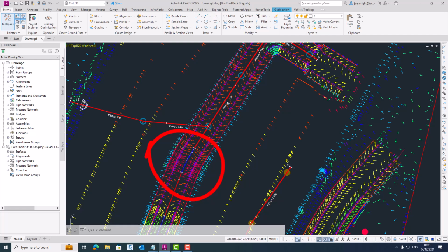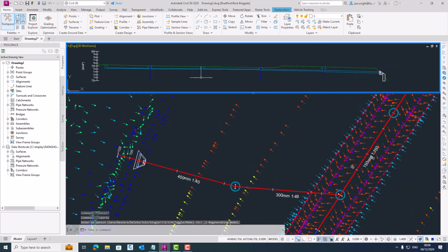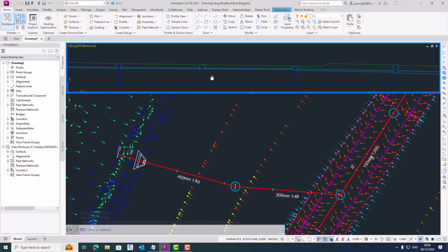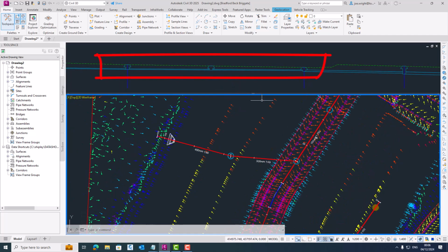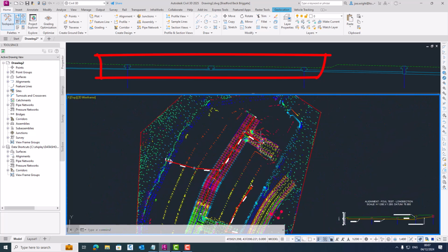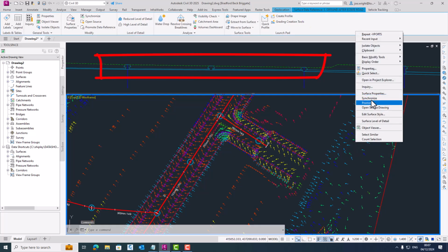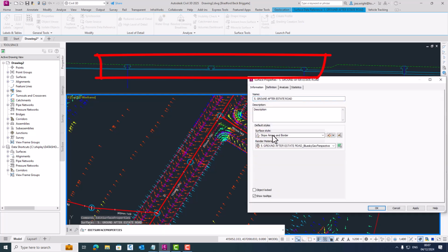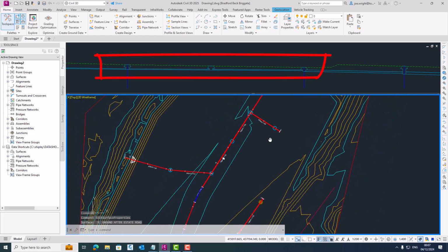Now, what has this done to our pipe network? Well, the ground levels have changed, and our pipe network followed the crown of the road. So, as you can see, it's automatically adjusted the cover level of the manholes appropriately, and this is good. However, the soffit level of the pipes have remained. In other words, it's not reapplied the rules. And remember, folks, pipe rules rule.